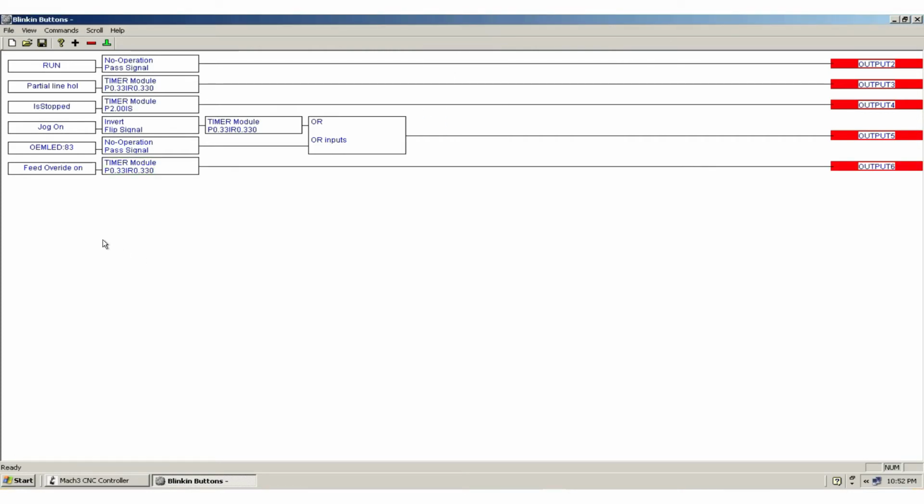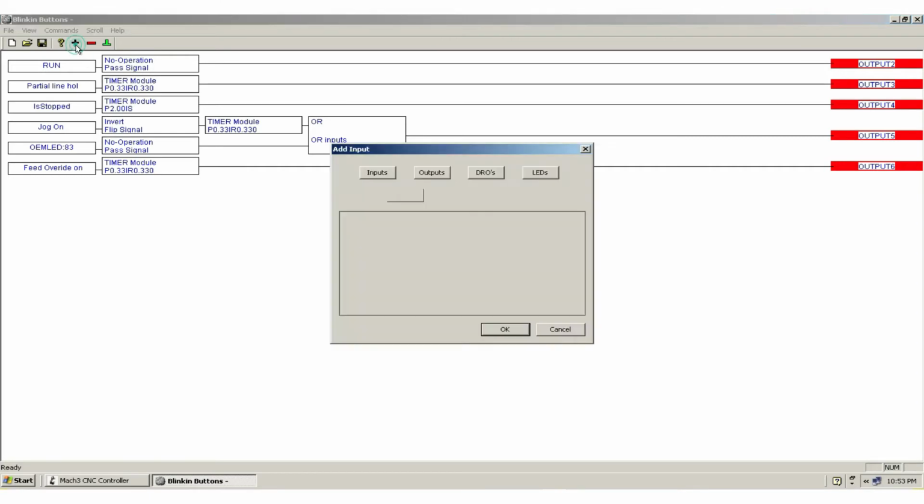Now for the E-Stop Reset LED, we have two different input signals, the virtual LED itself, but also the E-Stop button that is hardwired to the machine. So we're dealing with two inputs and two totally different behaviors. And this was a situation that did not allow me to do this without the addition of external hardware to accomplish the desired result. Let me first write the brain part of it.